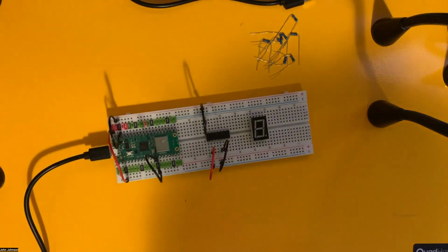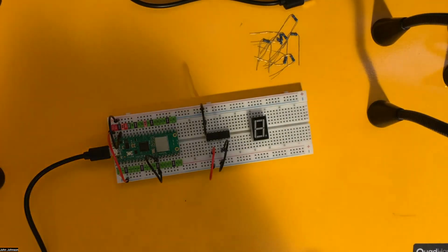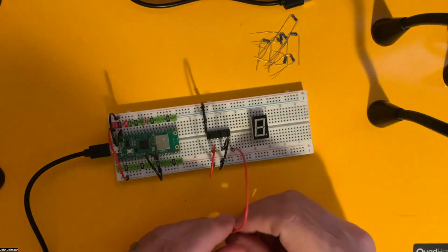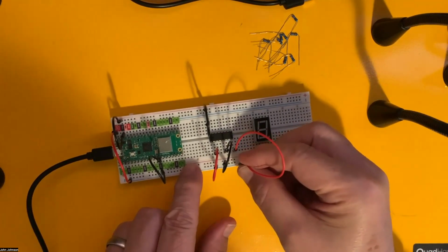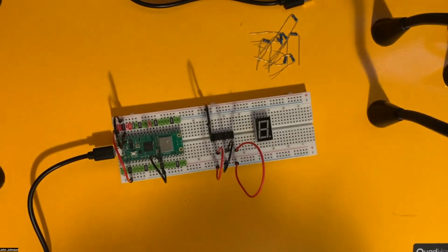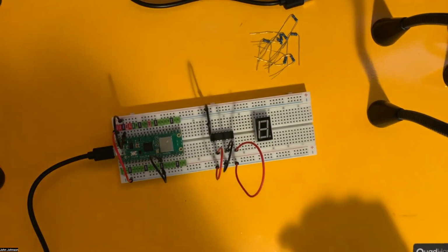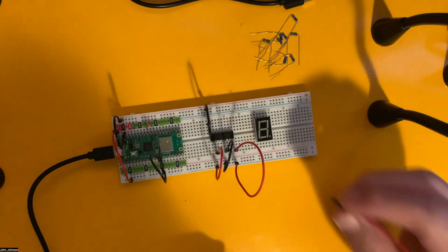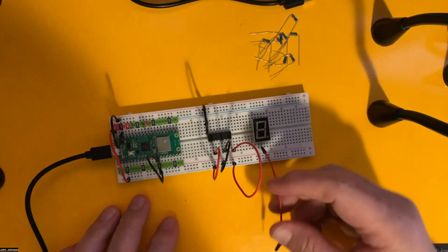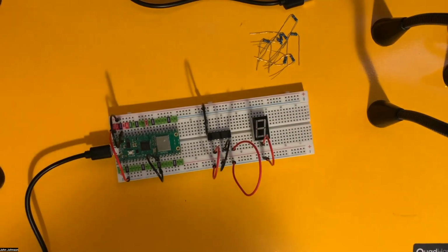We've got to do one more power. So we're going to do our power running from, let's see, the first pin on the right of our upside down chip. So we're going to run this into where? The outside rail, because our outside rail, of course, consistently is using our power. So now we're going to do one more power because we need power down here. So this one is going to be from the center, the third. So 1, 2, 3. So this will be from the third one, and we'll put this into, where is it going? The outer one. So there, we've got power running there properly.